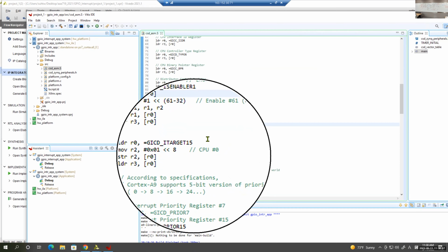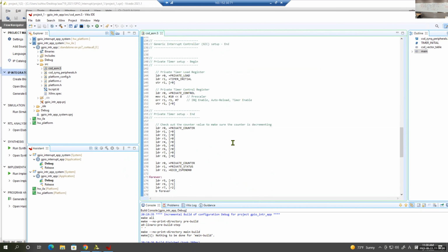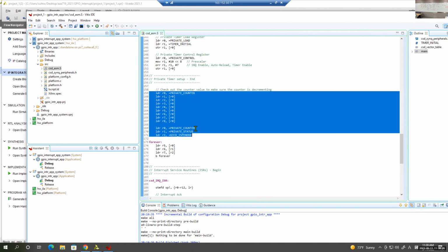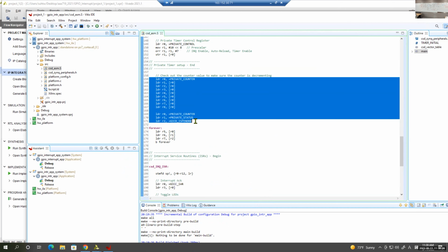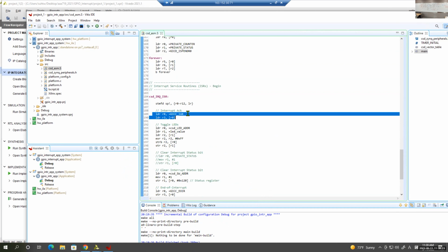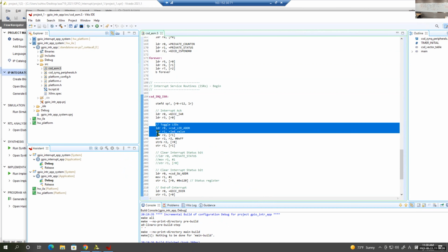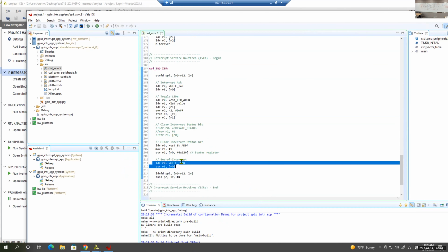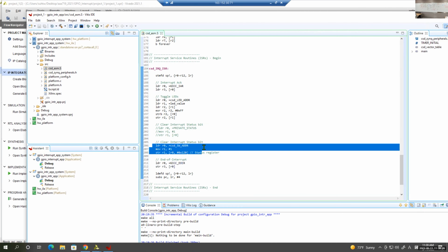Okay, then in ISR, what I'm doing is, okay. So I left this timer. It has nothing to do with that demo timer setting. Don't worry about that. In ISR, I'm reading acknowledge register, okay, and toggle LED. Then end of interrupt register programming. And before that, GPIO status clear. Okay. So let me show you a demo. Then come back to you.